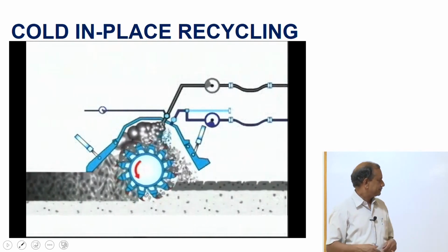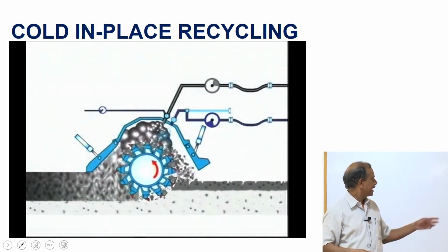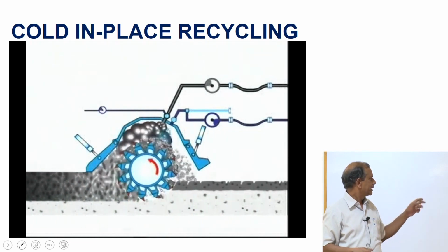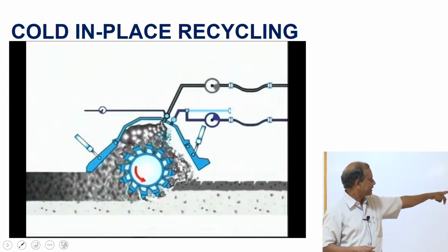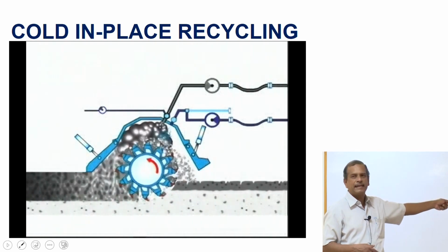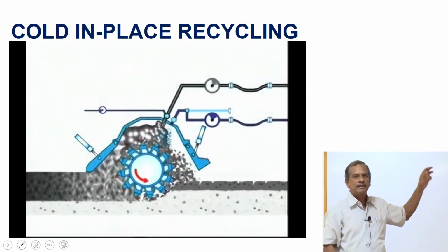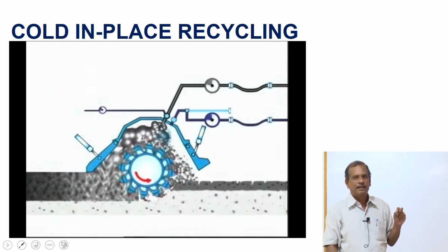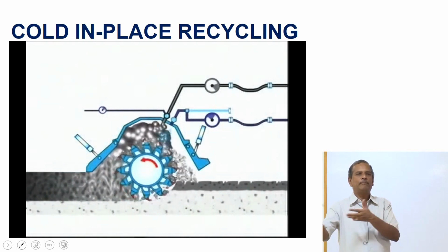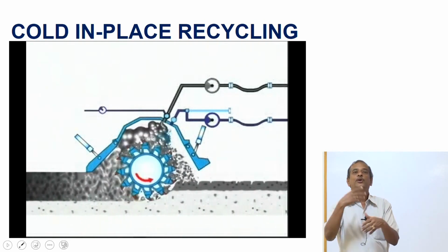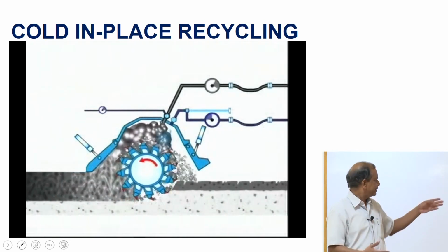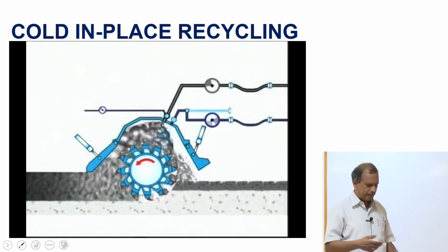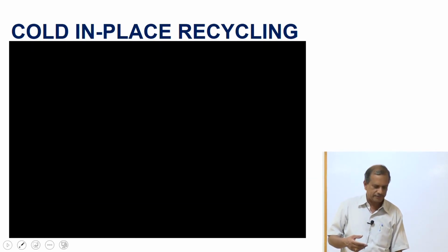I can mill the material. I inject the foam bitumen. So this layer is called a bitumen stabilized material, or BSM. So I have not thrown out the whole deteriorated pavement material. I am trying to reuse it again. Because the material has deteriorated, I am trying to strengthen the material properties by using a foam bitumen. I can reduce the thickness of the layers.